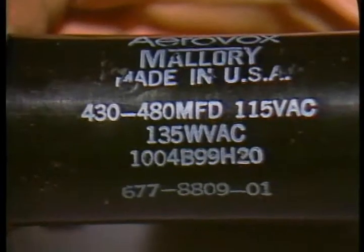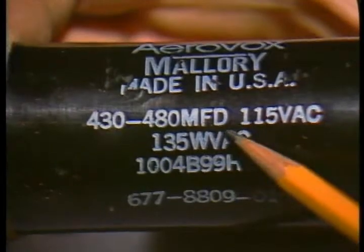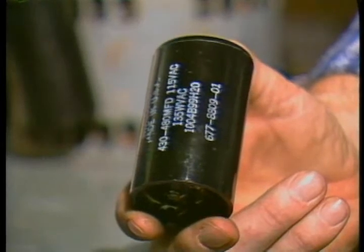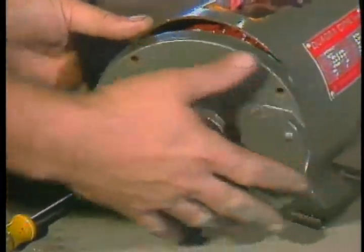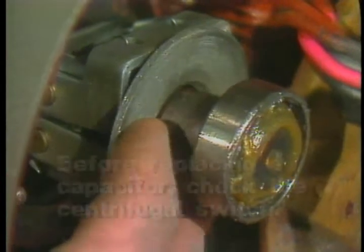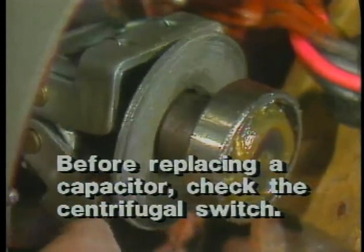To provide an adequate phase shift, the capacitor used has a very high capacitance. In order to keep it a reasonable size, it is an electrolytic type, made for intermittent duty only. It would soon short out if left in the circuit, so the centrifugal switch has got to work. If you find a motor with a bad capacitor, do not just replace it without checking to see that the centrifugal switch is operating properly.